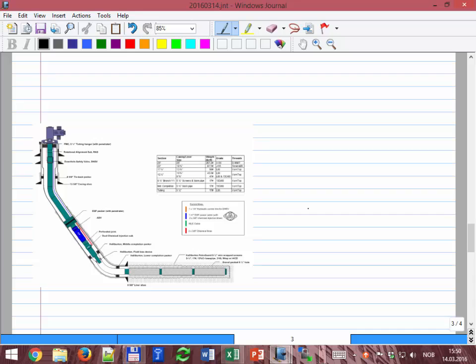All of this we're going to represent as a linear IPR, and then we have all the way to the suction of the pump. So this distance will be H1, and I'm assuming just that it's vertical, while in reality it is not, but it doesn't give any additional complication. Then we have the pump discharge someplace here and all the way to the wellhead. So again, that distance is H2.